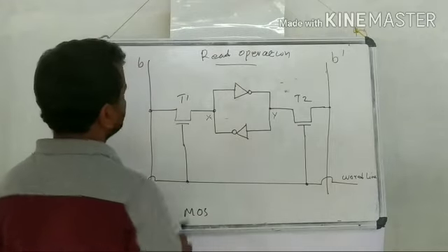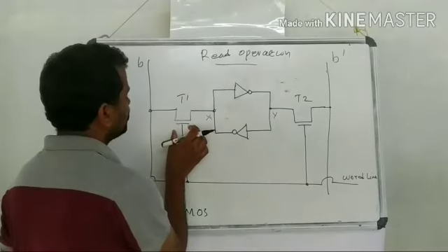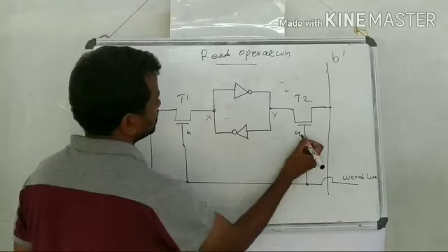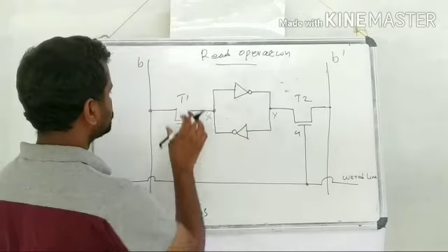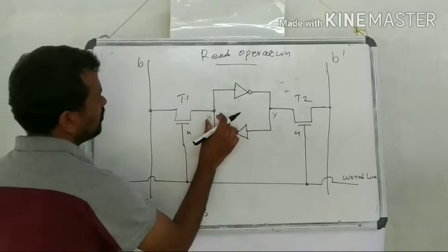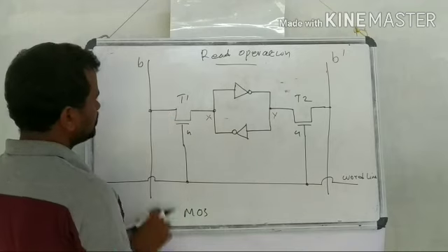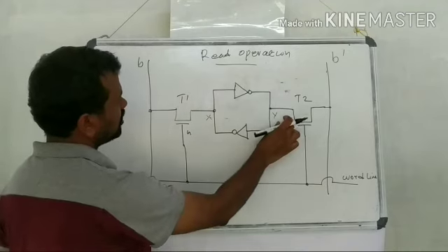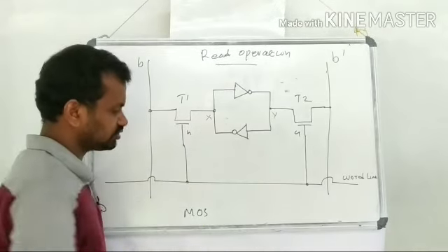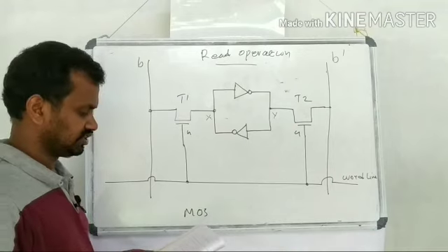So the transistors T1 and T2 will be turned on, because the gate input to T1 and T2 becomes high. The value at point X will reach bit line B, and the value at point Y will reach bit line B bar, and that goes into our sense amplifier or sense write circuit.